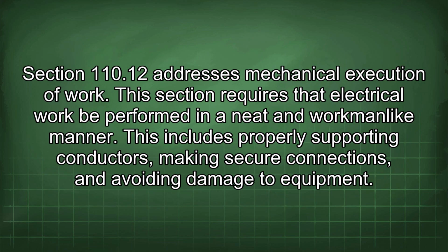Section 110.12 addresses mechanical execution of work. This section requires that electrical work be performed in a neat and workmanlike manner. This includes properly supporting conductors, making secure connections, and avoiding damage to equipment.